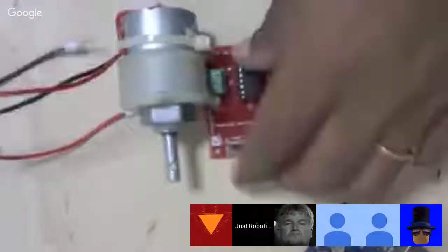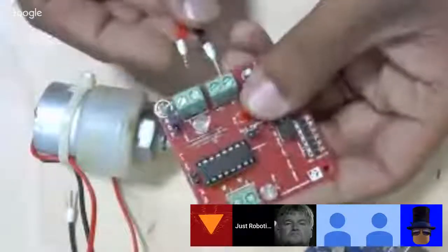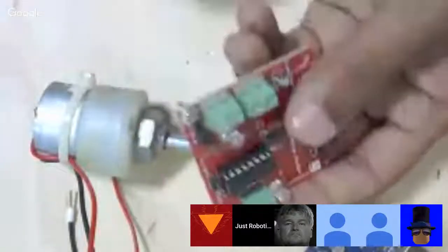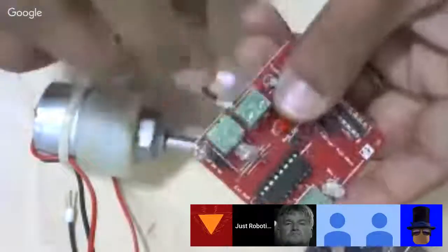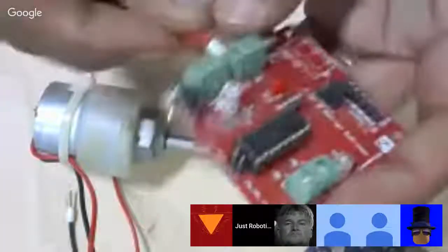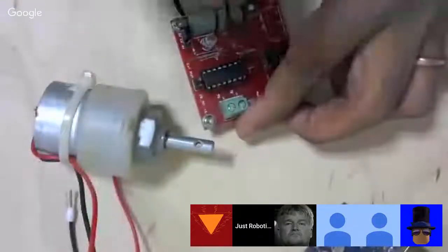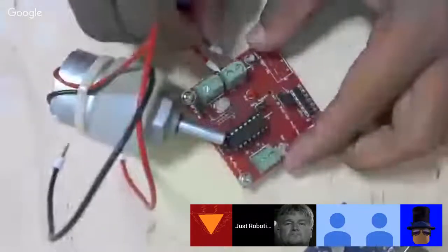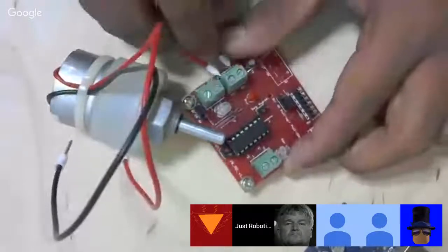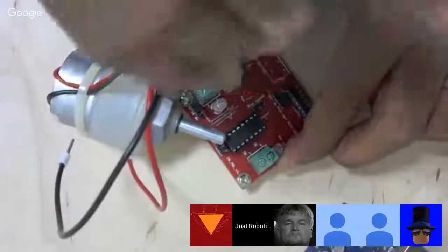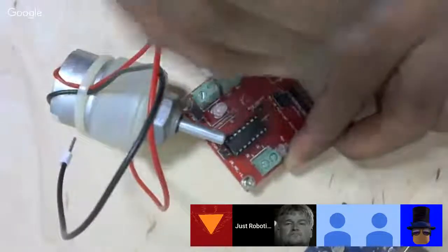First thing that I'll do is I'll connect the battery clips to the board. I'm sorry that the board looks reversed because of the mirroring of my camera. I've not got this other software to reverse it, but then I think that should be fine. For now, because it's not the first time we're doing this, I connect the red wire of the battery to the positive, and to the negative, I connect the black wire of the battery, or the negative terminal of the battery clip. And then I connect my battery.